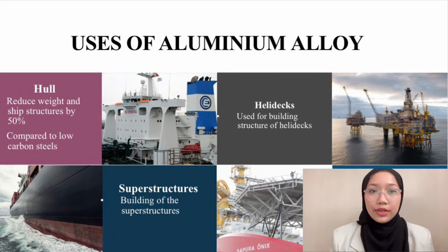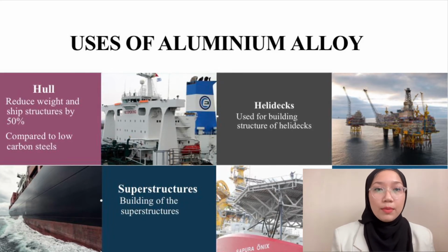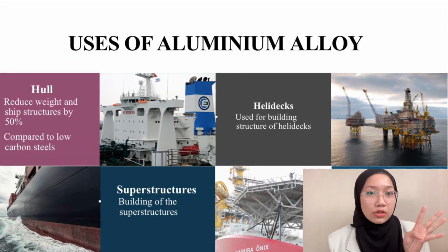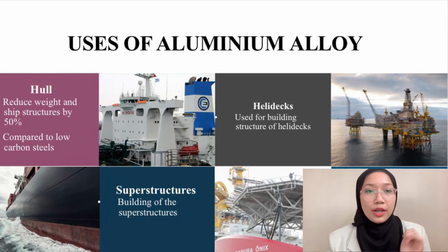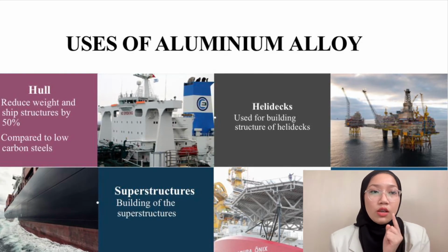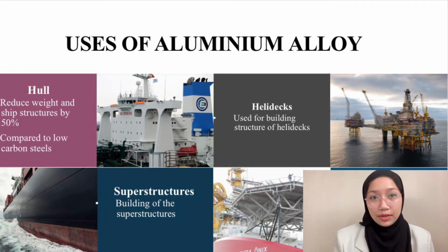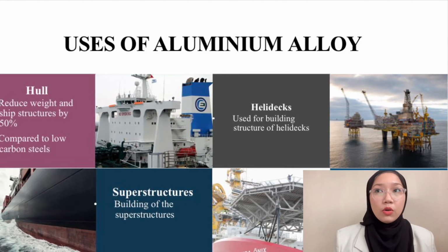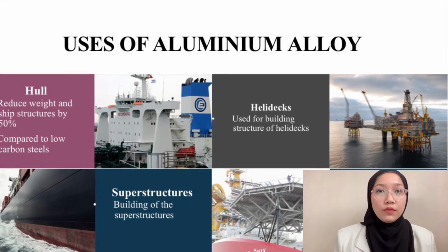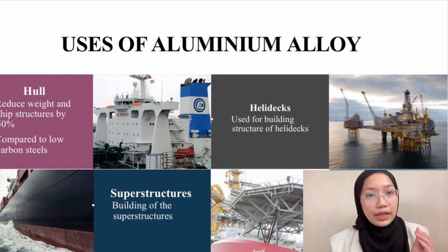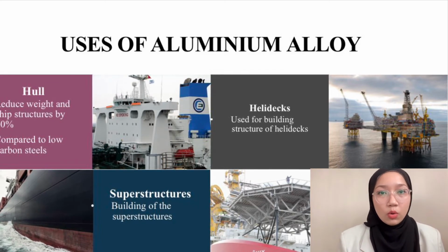Now, I will be talking about the uses of aluminium alloy. I'll be giving you 4 examples of aluminium alloy in marine applications. The first one is the hull. So what are the functions of aluminium alloy in building hulls? They function in reducing the weight of the ship structures by 50% compared to low carbon steels.